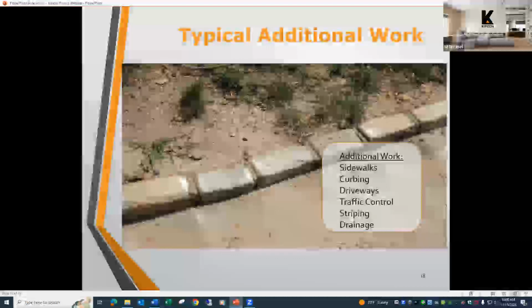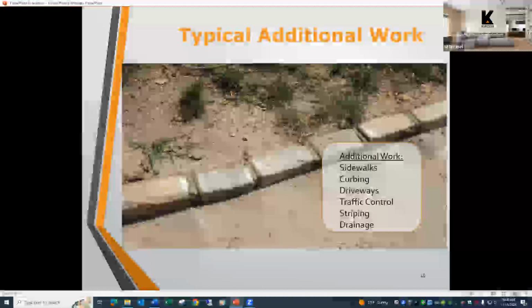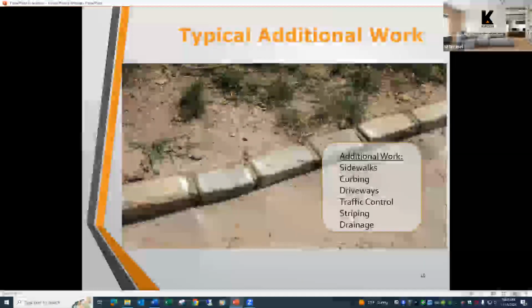We usually recommend that at the pre-construction meeting, once you've got your contractor lined up and he's ready to begin work, we walk through with the contractor and mark out the areas of curbs that should be replaced, and they replace that as part of the project. We don't quantify curbing when we're doing the specification, only because as that curbing overwinters, the plows hit it, and further deterioration from salt can occur. So it's better to mark out and quantify curbing right before you begin your project.